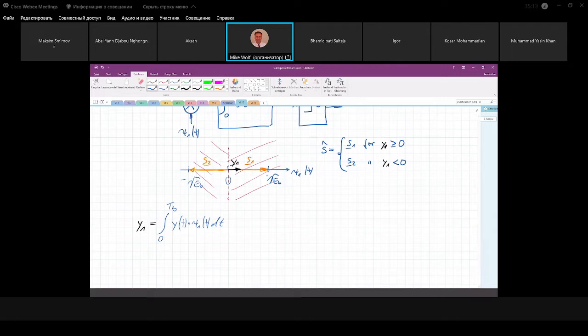You could interpret this, maybe I write this in this figure. If I transmitted s1, for this received vector the noise vector would have been this one. I just draw it here. There is one possible noise vector. If s1 has been transmitted, this would be the corresponding noise vector, the mapping of the noise into our signal space. But if s2 has been transmitted, which is possible, then the noise vector would have been this vector.